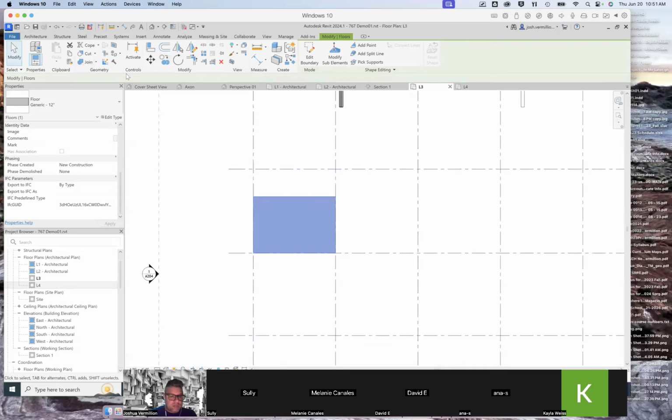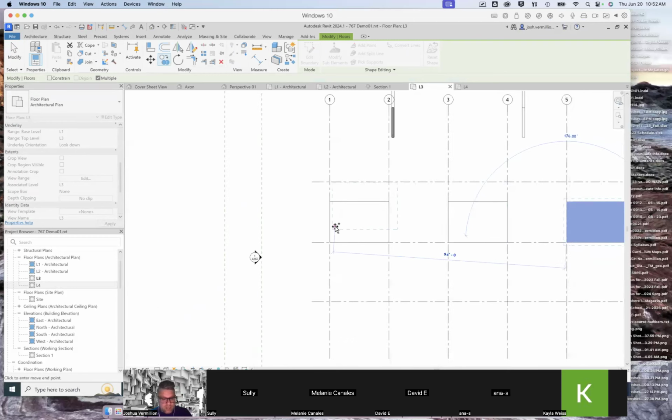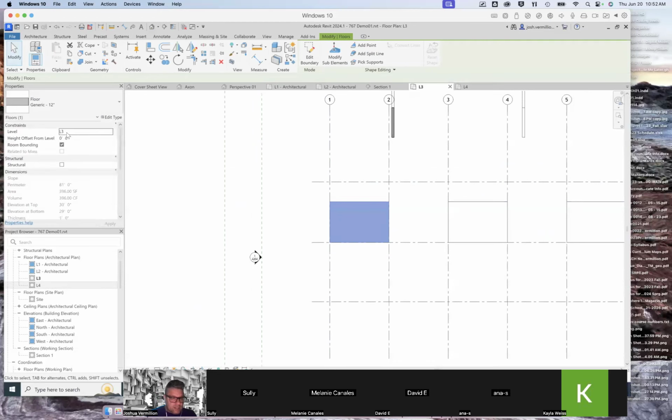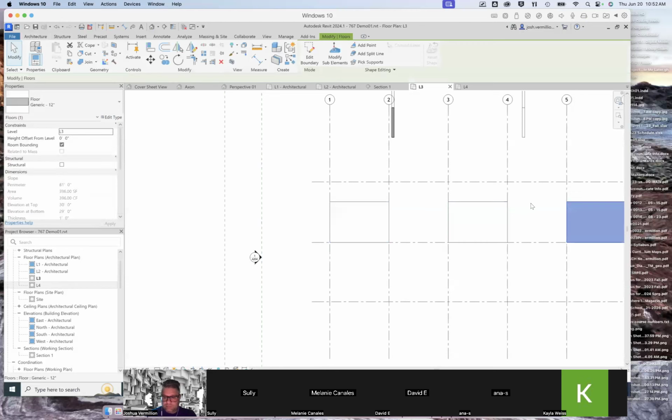Now I'm just going to make several of the same. I could copy that. I think there's a copy here. I'm just picking each time, and I assume I can just hit escape when I'm done. There we go. Now I have this, this, and this. Of course, I wasn't really careful. I didn't make sure that I had 12-inch selected and that it starts on level 3. Before I started making copies of it, I probably should have done that, right?